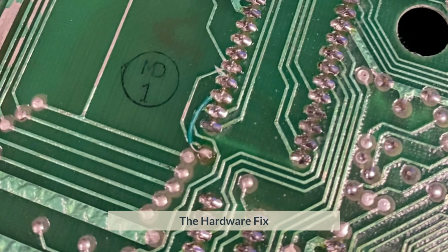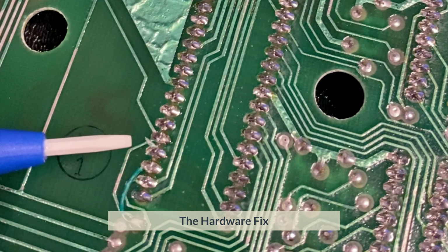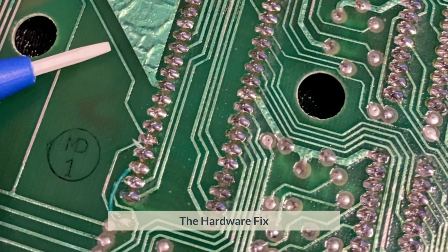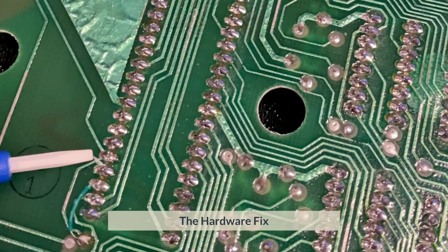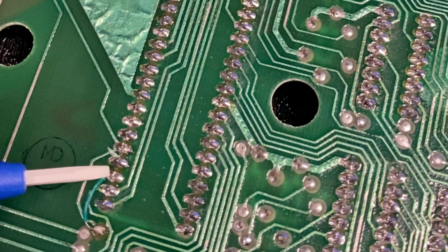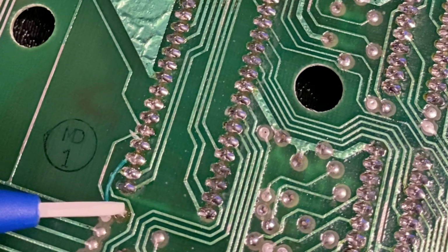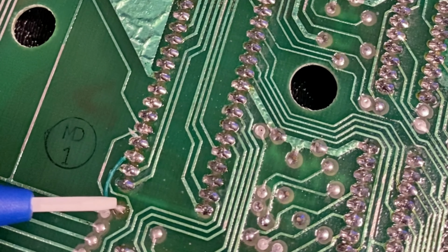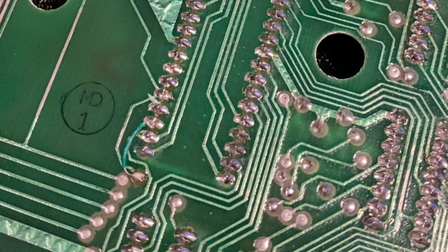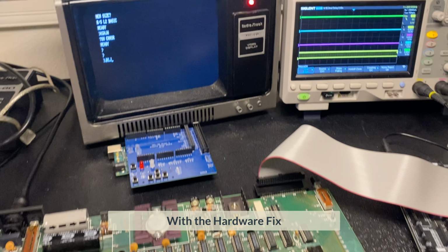Now a quick view on the hardware fix. So here there's a small cut for this trace. This is the test trace, which comes directly from the edge connector. A cut here, and then this is the bus request pin, and this pin is the bus acknowledge, which then connects to the rest of this. This then disconnects all the buffers. Now everything is reconnected with the hardware fix.